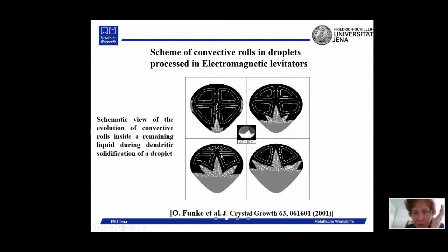And we can see, in principle, we almost always have flow directed in the opposite direction to the growth. Streams are directed down around the dendritic tips, and the dendritic tip grows up in the droplet. So in principle, this scheme works properly in many cases of triggering solidification.